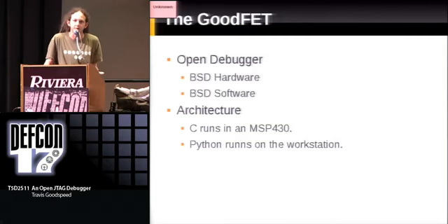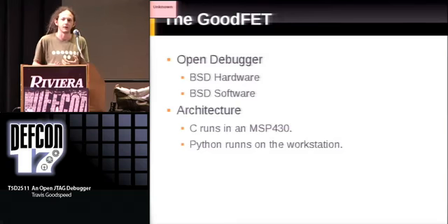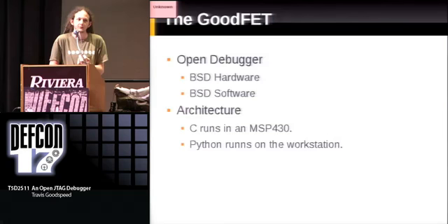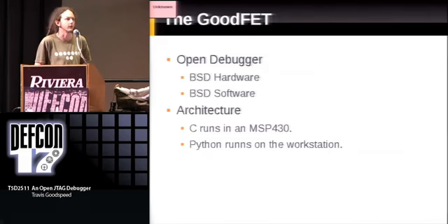This is compiled by GCC. To compile the firmware, link it, install it, and restart the machine to be executing it, you just type make install. It's quite neighborly in that regard if you're used to the Unix environment, because you don't need to deal with the embedded development tools or IDEs that are specific to each chip. So you don't have to know anything about the MSP430, which I use on this board, in order to begin adding support for new protocols.